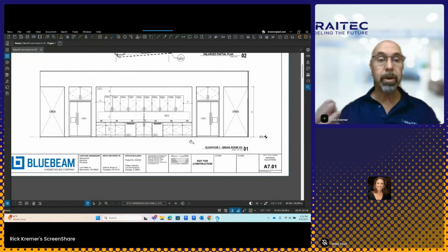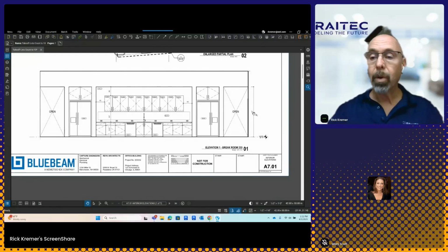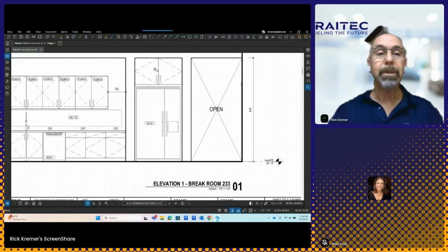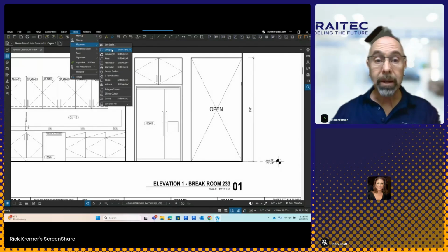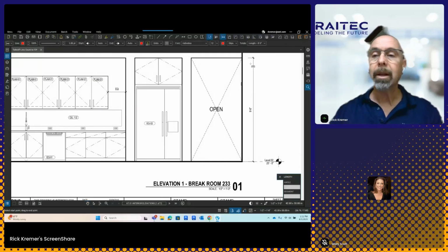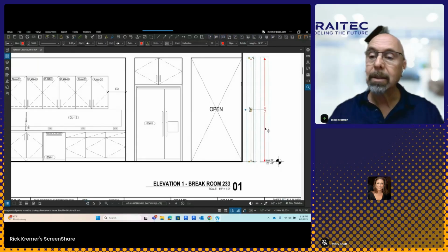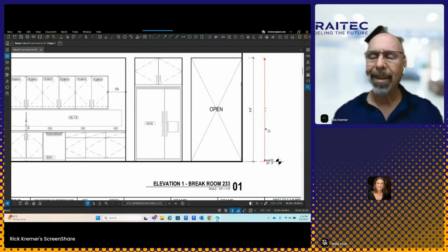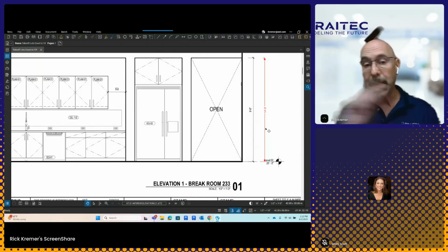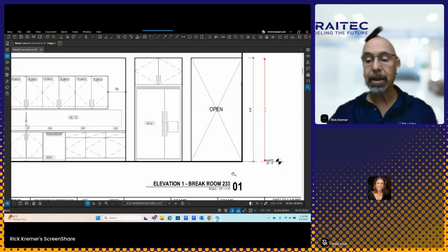So what do I do before starting to take measurements? Check to make sure that it is accurate. So over here, this should be 9'6". So I'll go to tools, measure, length, just to run a dimension check before I start to do area calculations. I'll click length and I'll go from here straight down. And if I take a look at this, what? That's 14'3". So my measurements will be completely off because this is not printed out at 1/2 inch.